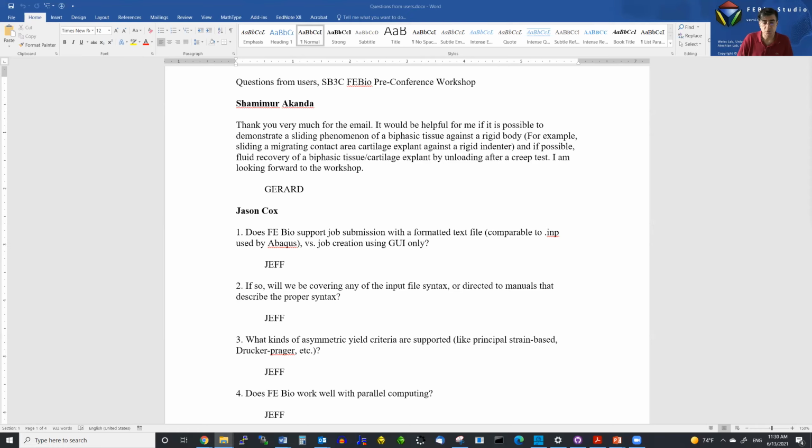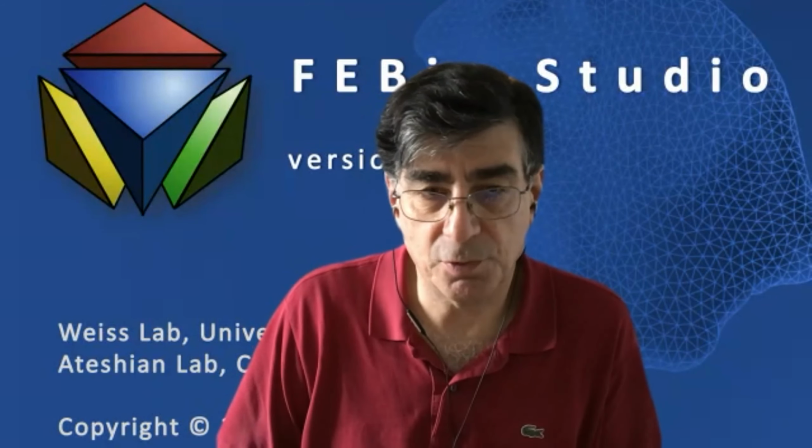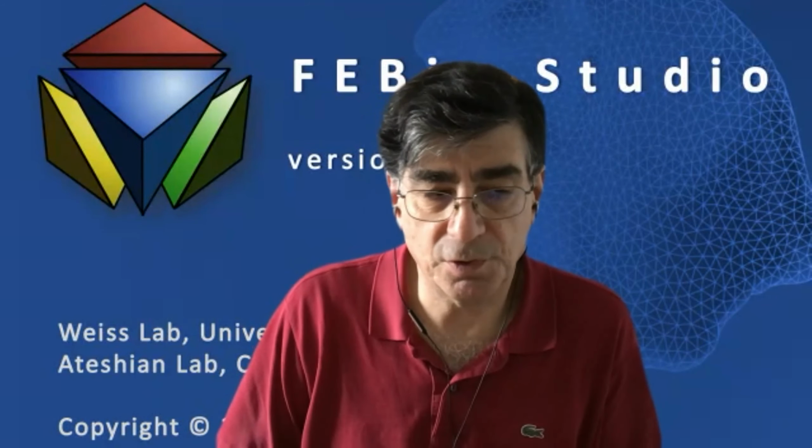Right. So Shamgar, originally I figured I could just do a demonstration in a breakout room with the two of us, but we decided for now we're not going to do the breakout room. So I'm just going to share with you the model that I created and explain the basics. You wanted a rigid indenter, so I created a sphere, and then I extracted a portion of the sphere's surface, and because it's a rigid material, it doesn't matter if it's a shell element or solid elements. And this is a biphasic layer.